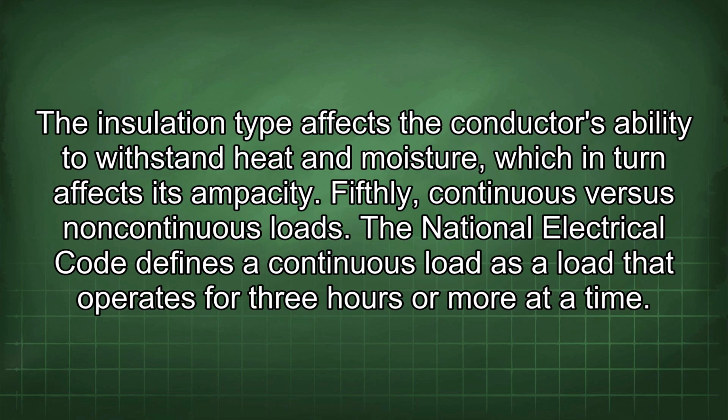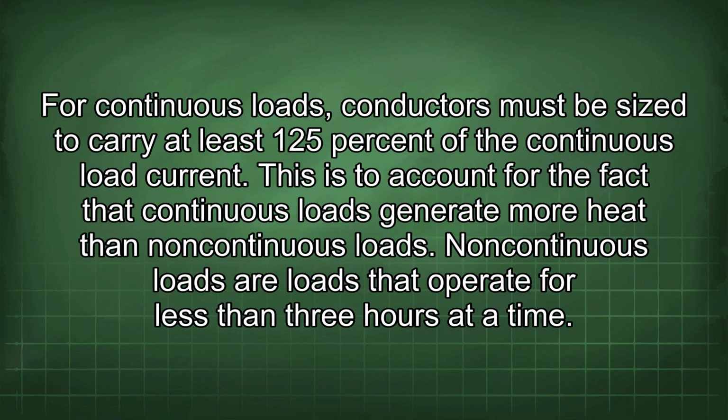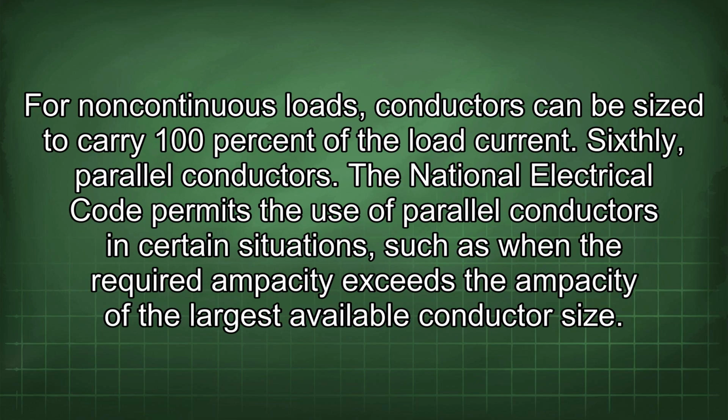The National Electrical Code defines a continuous load as a load that operates for 3 hours or more at a time. For continuous loads, conductors must be sized to carry at least 125% of the continuous load current. This is to account for the fact that continuous loads generate more heat than non-continuous loads. Non-continuous loads are loads that operate for less than 3 hours at a time. For non-continuous loads, conductors can be sized to carry 100% of the load current.